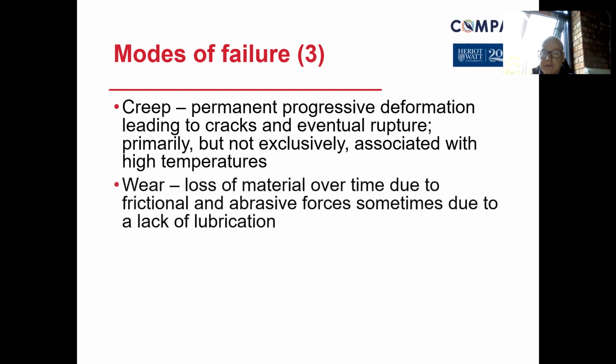Wear is the loss of material over time due to frictional and abrasive forces, sometimes due to a lack of lubricant. Again, a classic one for me is the mortar between bricks. You'll see bits of the mortar breaking off, and perhaps it needs to be repointed.